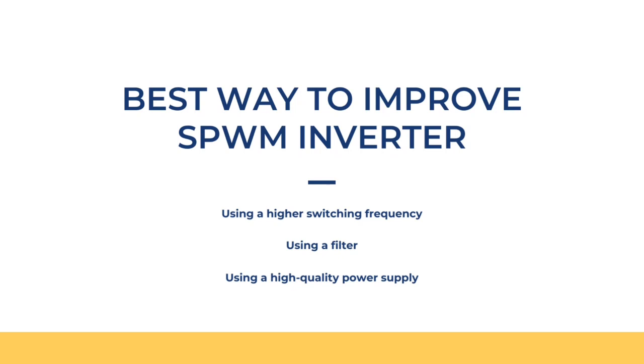Okay, for the second point, using a filter. A filter can be used to remove the harmonics from the output waveform, leaving a pure sine wave. There are a number of different types of filters that can be used, including low pass filters and band pass filters. The type of filter that is best for a particular application will depend on the harmonics that are present in the output waveform. For the third point, using a high quality power supply. It will reduce the noise and interference that can corrupt the output waveform. This will also help to reduce the THD levels.